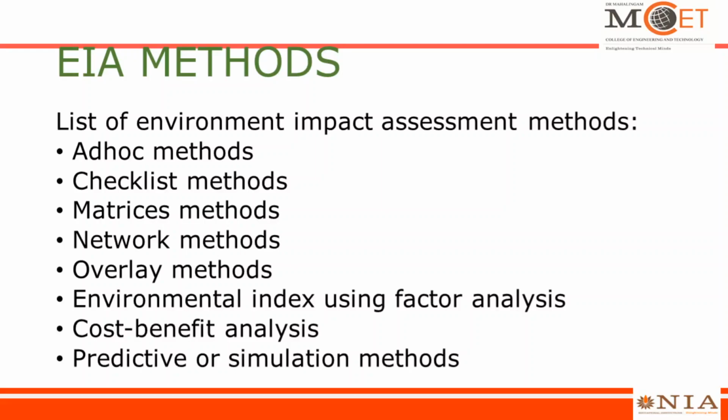We need to know the topography. We need to know whether the elevation is flat or sloping down. If it is sloping down, simply recharging that zone is not going to be of any use. Why? Because water is going to go down the slope. So you'll have to get all these layers and overlay them, and then you will be able to find out the best recharge location for a particular locality. So that is a simple explanation of what the overlay method means.